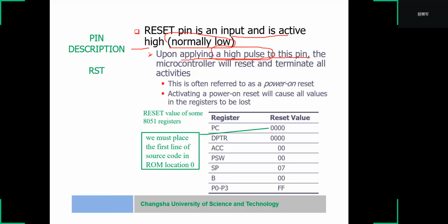The 8031 and 8032 family members do not have on-chip ROM, so code is stored on external ROM and fetched by the 8031 and 8032. Here, the EA pin must be connected to ground, indicating that the code is stored externally.